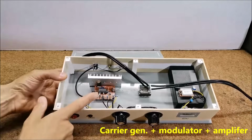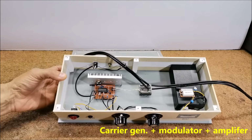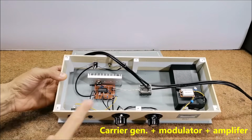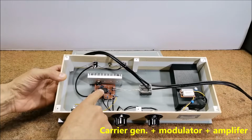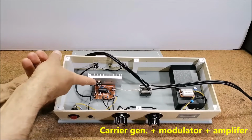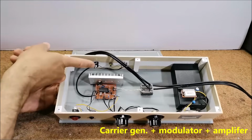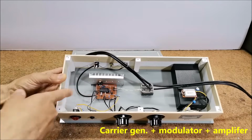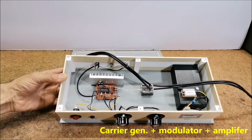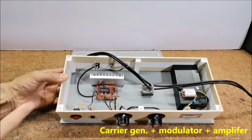Next part is the carrier frequency generator with modulator and amplifier. For this purpose I use a TL494 PWM modulator integrated circuit and an IRF740 or similar power MOSFET transistor as a signal amplifier. At the input we bring the signal from the PC sound card, which is actually the Rife frequency that is modulated by the carrier.